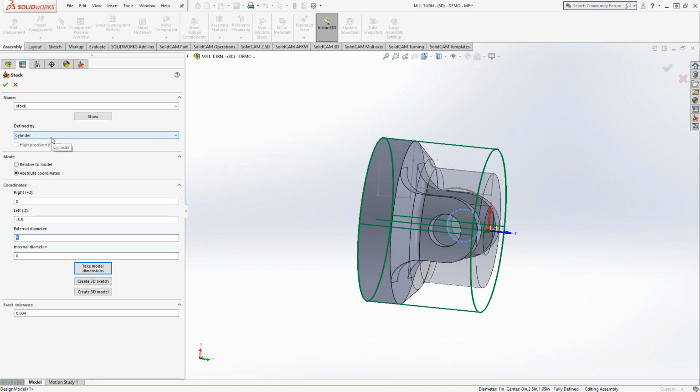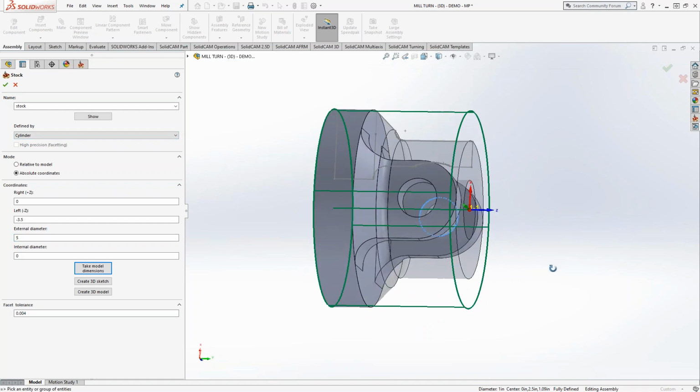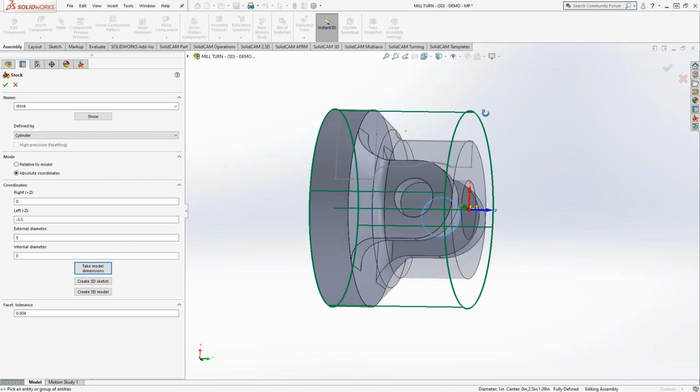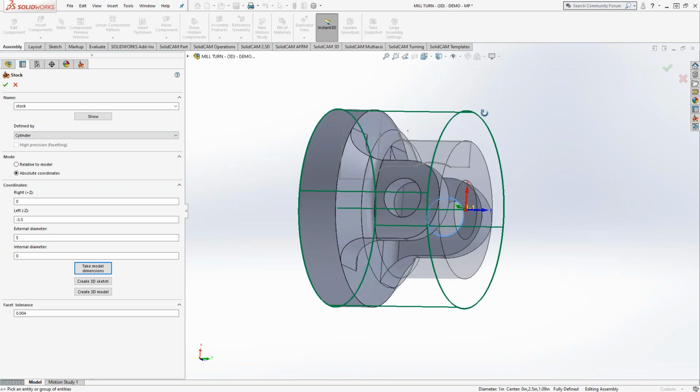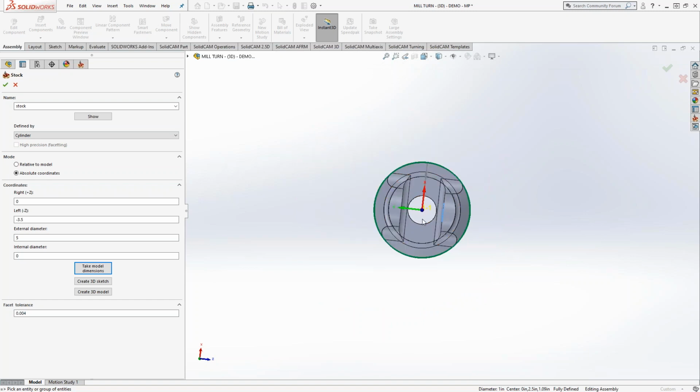And again, this only really works for when you have the Z-axis dead center of your part. You can do the cylinder definition in milling as well, but that's only when it's top dead center, not usually when you have it on the corner. Otherwise, what you'll get is a cylinder that has a radius of basically the entire part. So if you had, let's say, top corner of model stock, you'd have a cylinder that has that entire radius there.